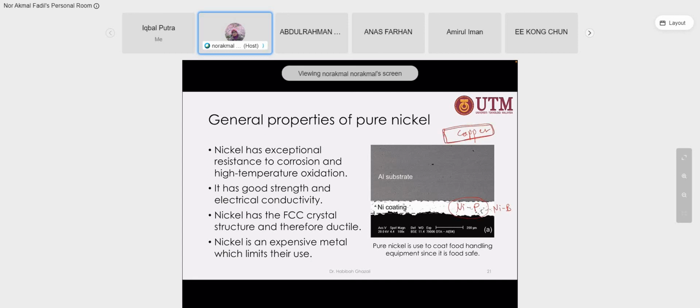And this copper we basically solder with soldering material. Mostly, the electric conductivity between these two interfaces is weakened over time, even at normal room temperature. So most of the copper surface is being coated with nickel. I think the coat is nickel to enhance the reliability of the joining. Any electronic component will be joined.